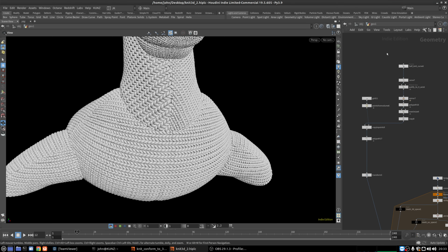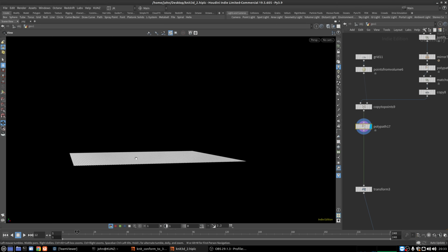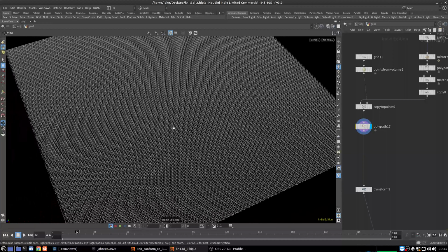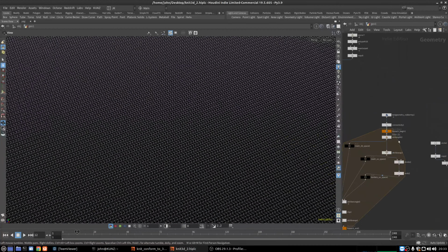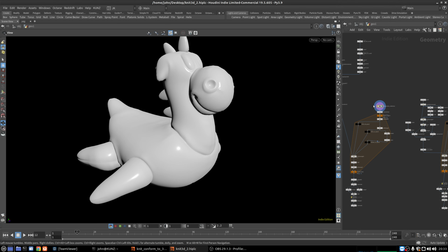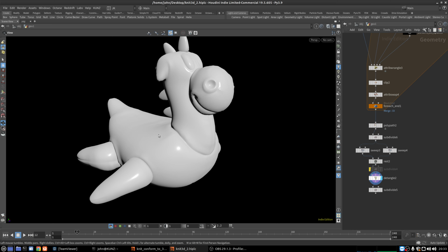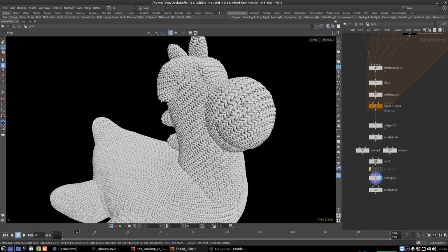And we're still working with our initial building blocks, or these modules that we've been setting up for this, just calling it a modular approach. So in this case, this is the original basic knit, and we're just using the default Rubbertoy test geometry. And then we'll be applying the knitting from 2D using UV coordinates to the 3D surface of the geometry. And we'll be doing most of this through Vex.